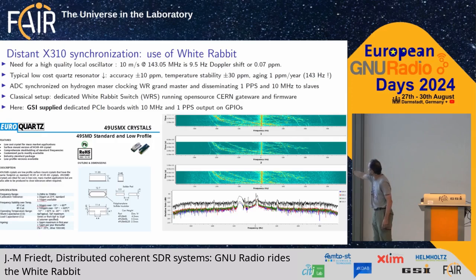When you've got these kinks over here, this means that the plane has turned and the projection has changed. And when you've got this big blob here, this is a fighter jet, because fighter jets don't fly straight, they just keep on moving in all directions. So your Fourier transform doesn't integrate into one nice peak in the frequency domain, but you've got a whole range of velocities. And this is actually a direct wave, direct from the GRAVES emitter to our receiver.